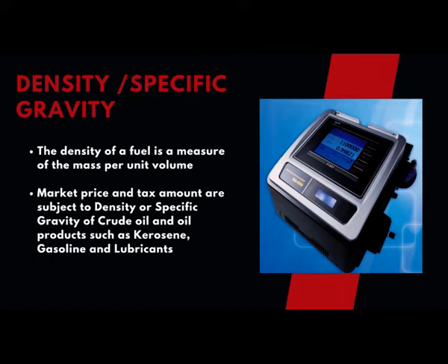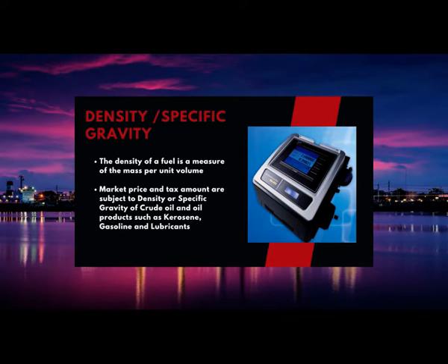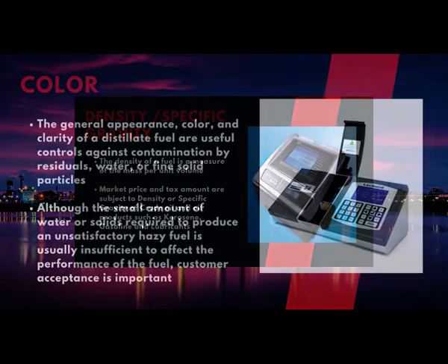So, generally the oil accounting is done on a mass basis, not on a volumetric basis. Most of the time we will directly calculate the volume stored in a tank, but unless we know the density, we may not be able to arrive at the mass stored in the tank. So, in order to calculate the mass stored in the tank, the specific gravity is important, and today there are sophisticated instruments through which you will be able to find out the specific gravity or density of a petroleum product in less than 1 minute.